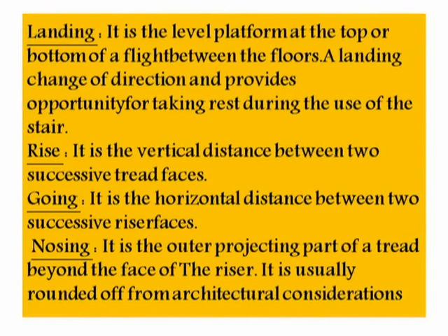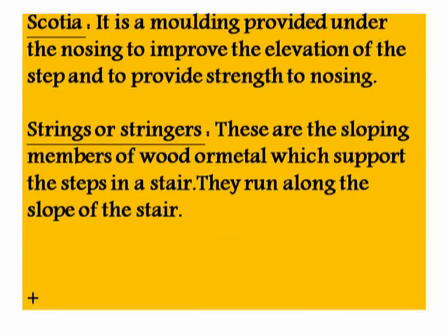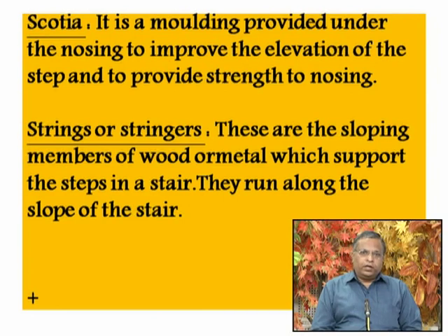So nosing is the outer projecting part of a tread beyond the face of the riser. It is usually rounded off from the architectural consideration. Nosing is provided from the architectural point of view. Scotia is a molding which is provided under the nosing.